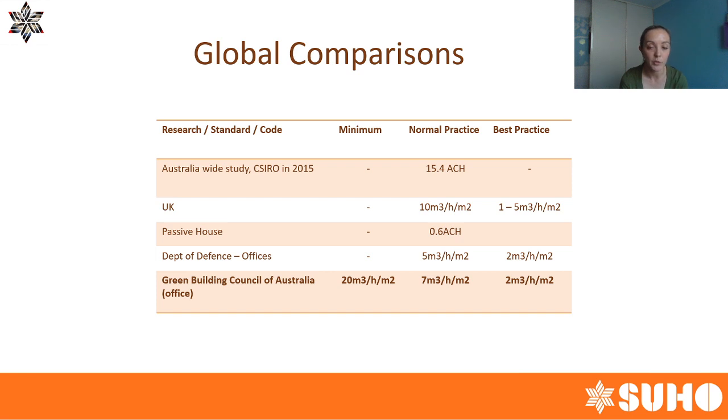You won't be aware of what you've actually accidentally done. And then the occupants in that building could be subject to poor indoor air quality. They could have problems with moisture buildup and mold in their home. So the build tight, ventilate right mantra is extremely important.